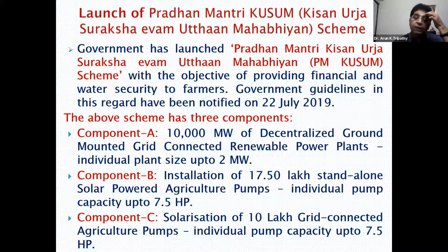Sir, I would like to elaborate that if a farmer wants to install a small solar power plant at their place, which is connected to the rural grid, he can generate some income, and that will be purchased at a fixed price. For this scheme, the fixed price ranges from rupees 6 per unit to rupees 8 per unit. So if a farmer installs, say, 1 megawatt of solar power plant, and that 1 megawatt gives about 1.5 million to 1.7 million units a year, you can multiply it by 6 rupees or 5 rupees.